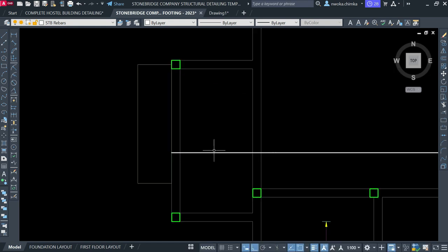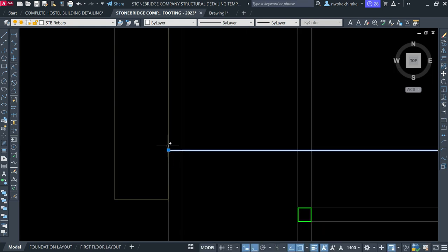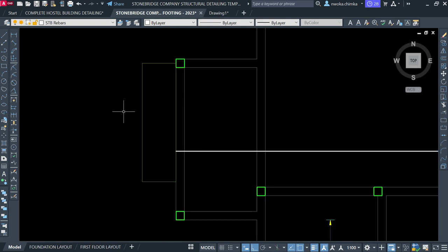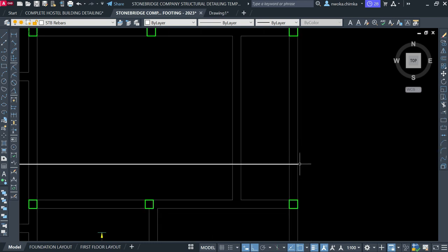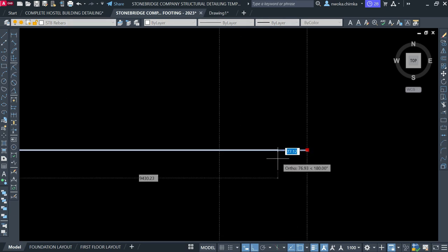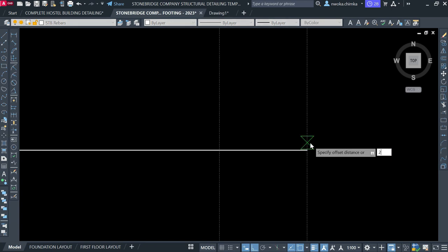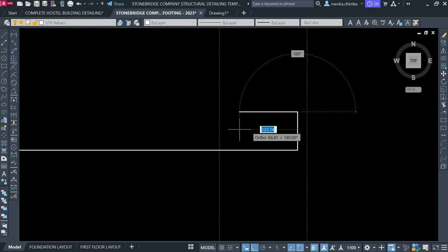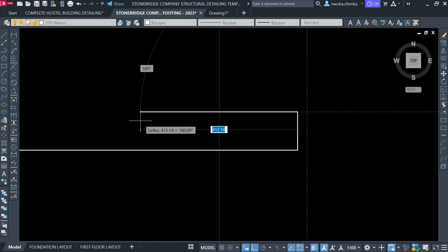And then what happens is that I'll have to make this bar to be here because this place is a cantilever, as you can see there right now. So I'll first of all come here first and then click on this place and take up my cover backward. I'll type 25. Either I'll offset the line by 25, this wall by 25, and then trim off this one first, and then remove this line immediately and click on line, enter, come here and type my 100, and then go here and type my lap length, which I've already showed you.